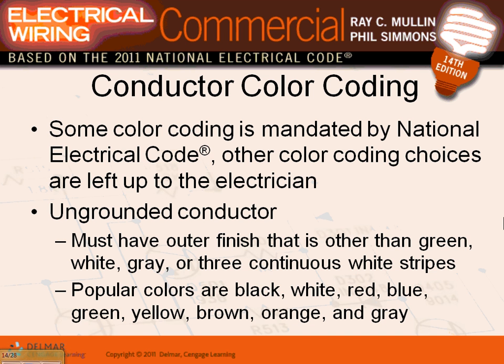Okay, moving into conductor color codes. I brought a couple of color coding conductors. When you deal with color codes, you're always dealing with a three-phase system. This system is commonly used for 208/120. This is what your building is going to look like, with wires like this. Black, red, blue, white, and green.